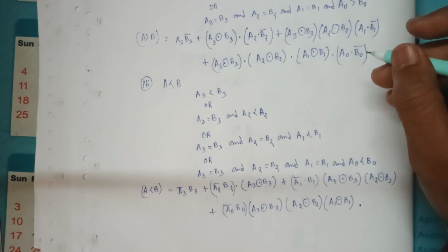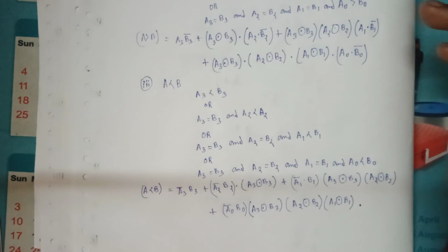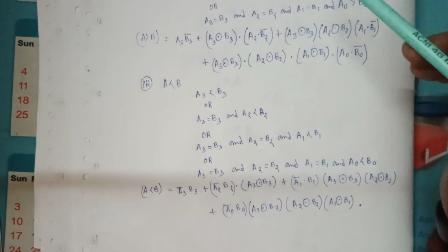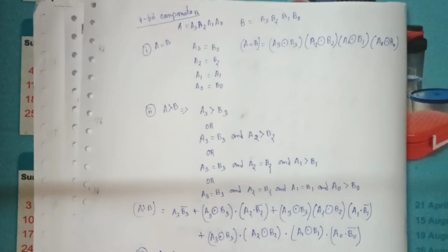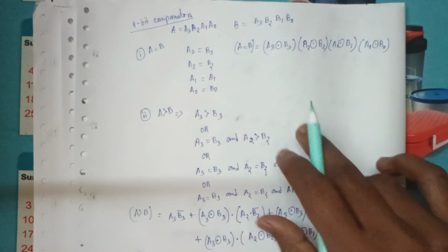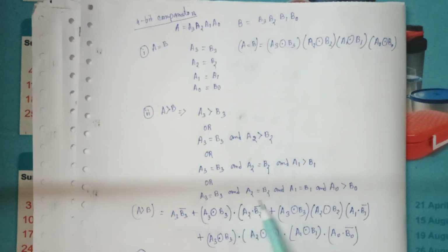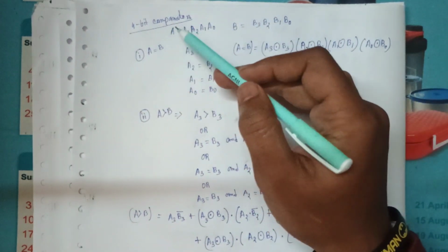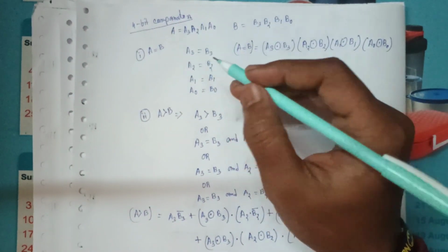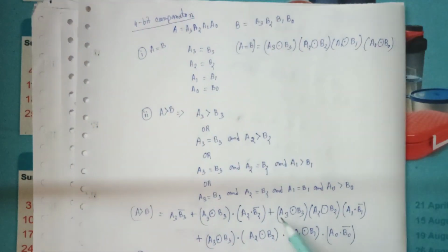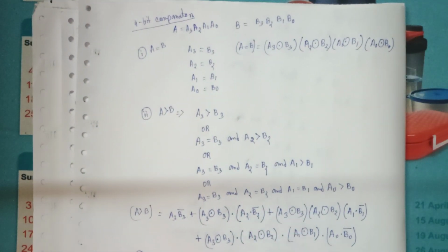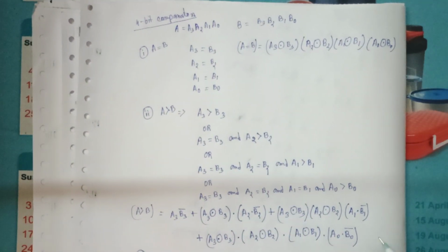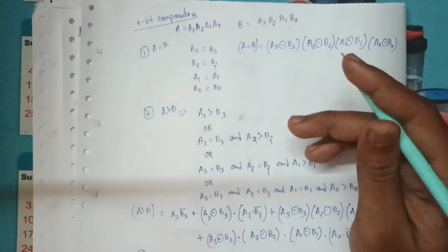To compare 4 bits, as you go further, you will see the logic expression gets massive. I have just shown four bits in the 4-bit comparator, and the circuit will be complex also. Like you can see here, to make it simple, we use the 7485 integrated circuit.